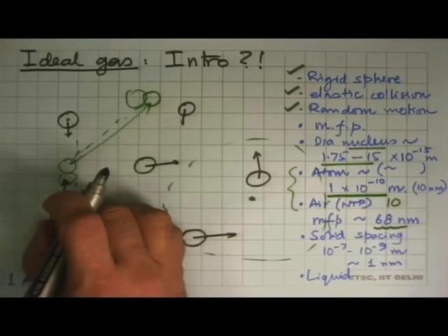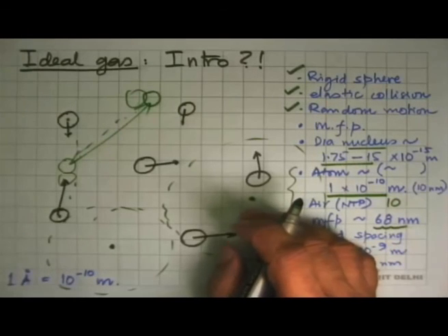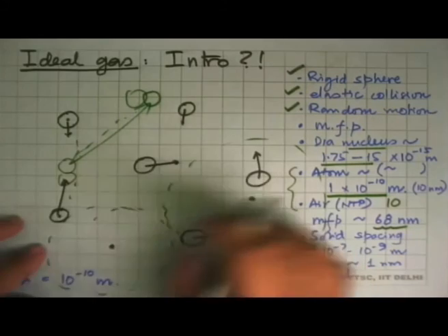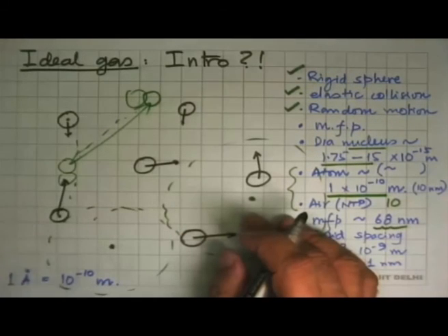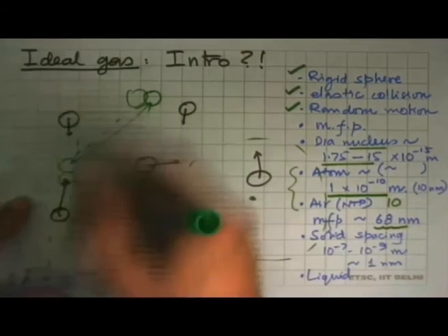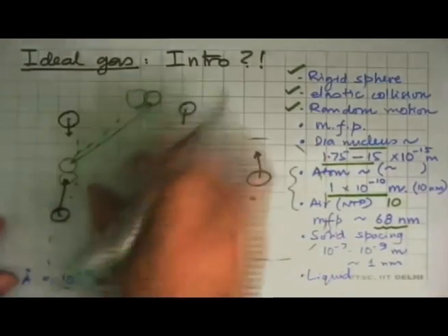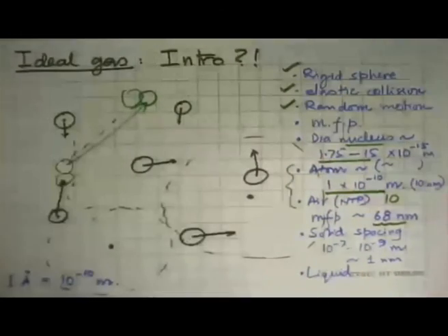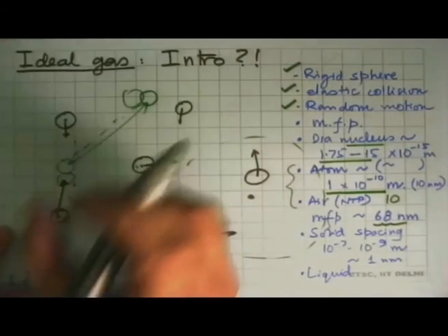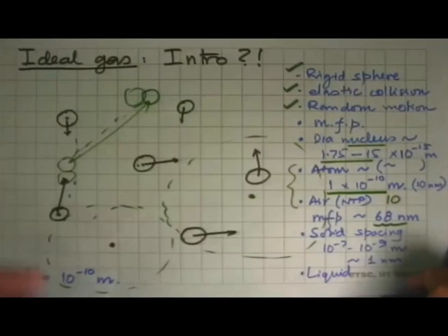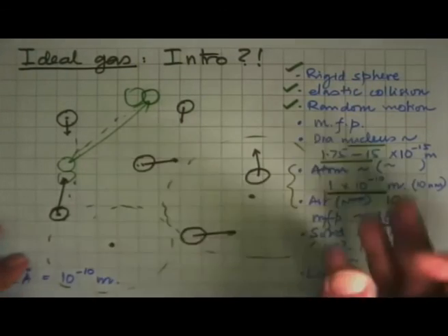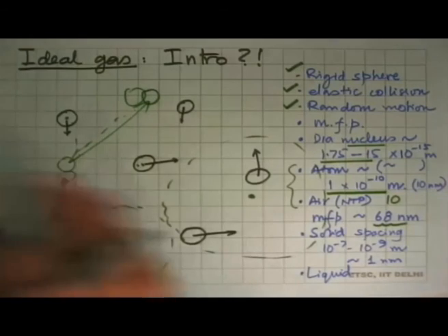And as you go for greater and greater vacuums, this distance keeps increasing. If you look at a satellite orbiting at low altitudes, the distance between two molecules that you will see there is of the order of several kilometers. So that's at the low pressure side. At the high pressure side, as you start pressing these things together, these molecules all start coming closer to one another. The intermolecular distance becomes less, the distance between collisions becomes less, and gradually you start deviating from ideal gas behavior to a real gas behavior, and then finally it is not gas at all.